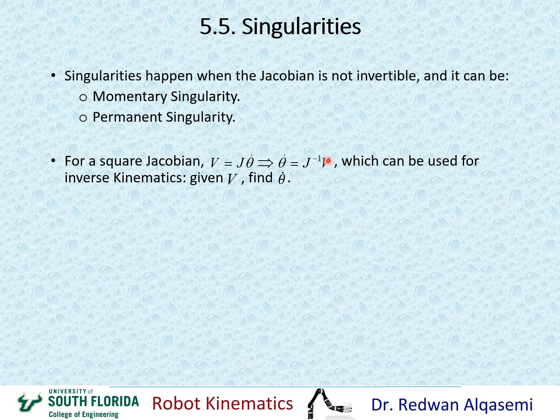Okay, so to find the inverse of the Jacobian, when we do inverse kinematics, we always have to check the determinant of the Jacobian. Because to find the inverse, of course, you have to divide the conjugate of the Jacobian by the determinant of the Jacobian. So the determinant of the Jacobian can be a good indicator of singularity. If the determinant of the Jacobian does not equal 0, that means J is invertible. Okay, so that's a good case right here.